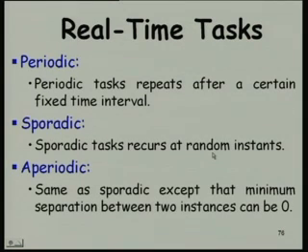Suppose we are monitoring the temperature, the sensor will monitor it and instead of sampling it periodically, it just sends a signal once it exceeds some value, or a fire condition or smoke condition being sensed. So, these are sporadic tasks, you can't say when they will occur, they may occur at random instants.